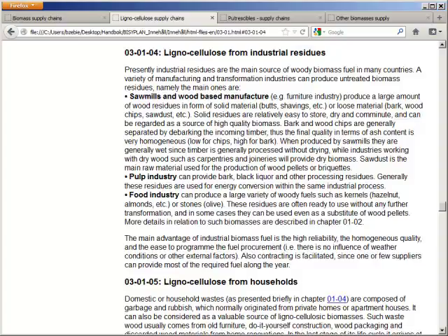This will also apply to the agricultural pellets that may be produced during harvest of a specific crop. The fact that there is a specific crop being harvested and that the pellets are produced immediately means that the raw material is uniform, the moisture content is uniform, the handling and hence the amount of extrinsic ash is also uniform.